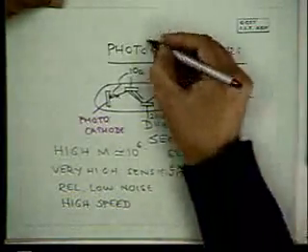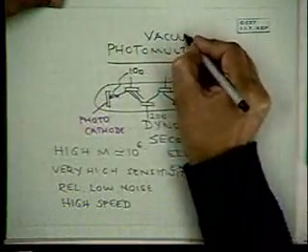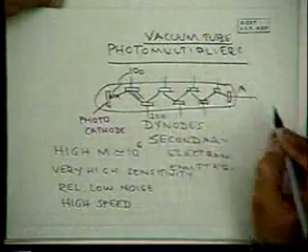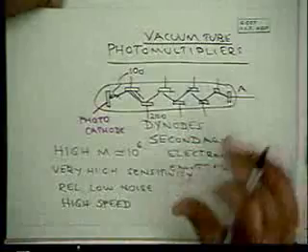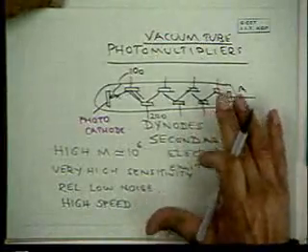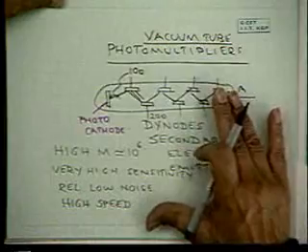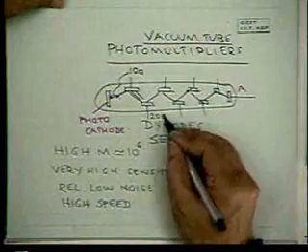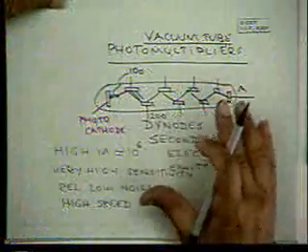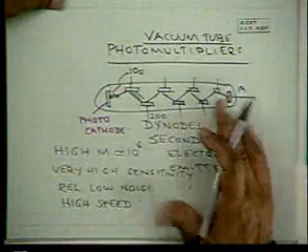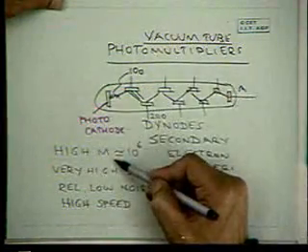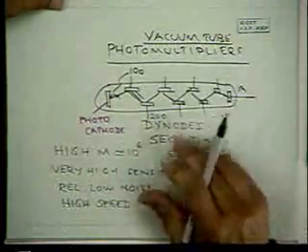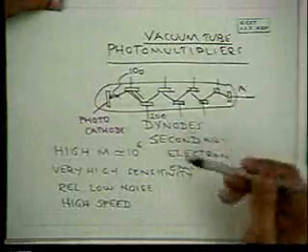So these are vacuum tube photomultipliers, which are extremely important in technology. And one of the aims of solid state devices is to try and develop a solid state photomultiplier which would imitate this and give the same properties and same response. In this connection, it is the APDs, avalanche photodiodes, which also give rise to gain, are highly sensitive, and are also fast, which are the analogs of these vacuum tube photomultipliers.